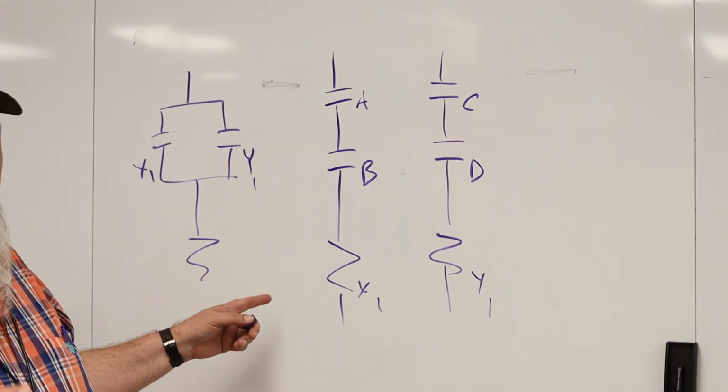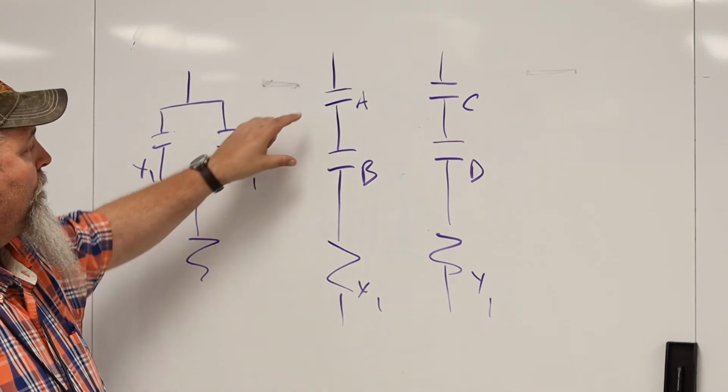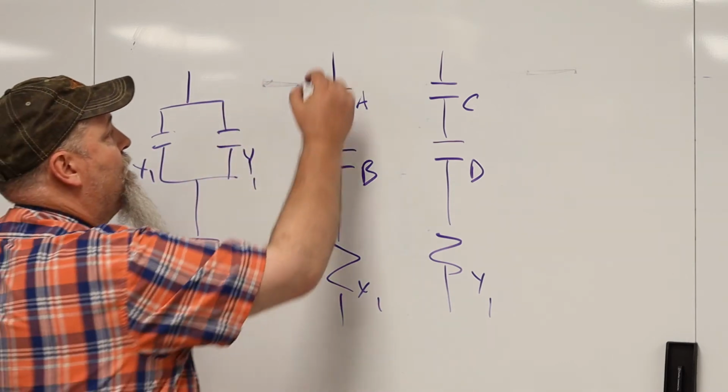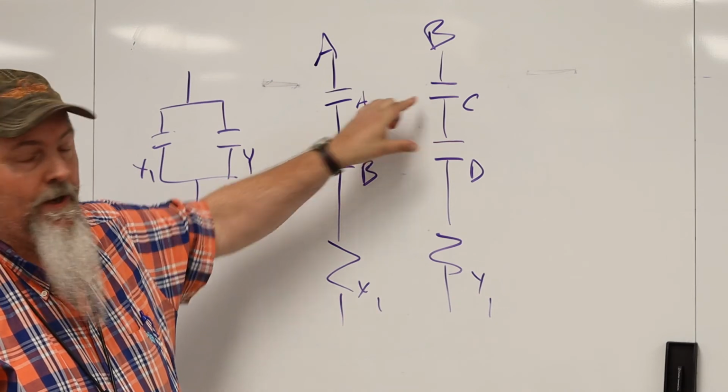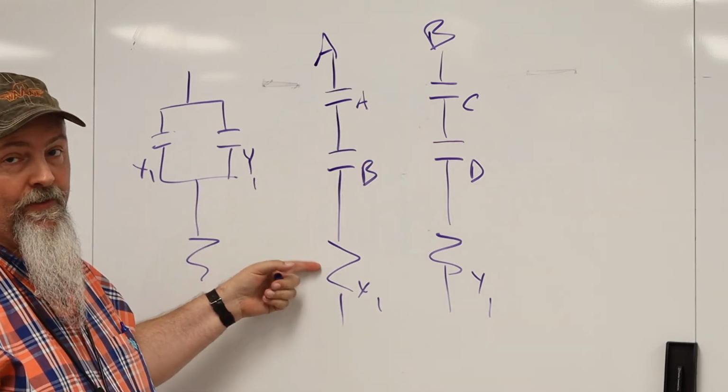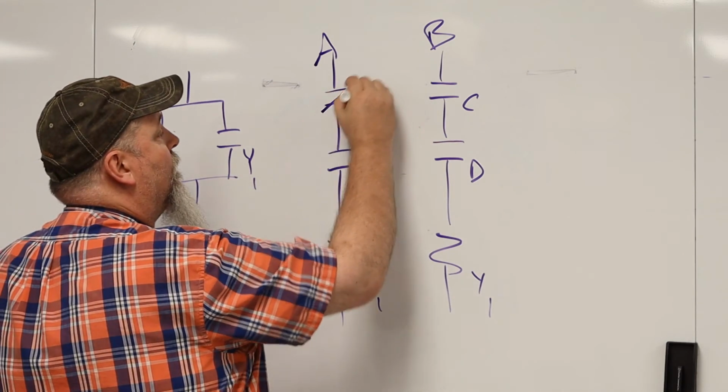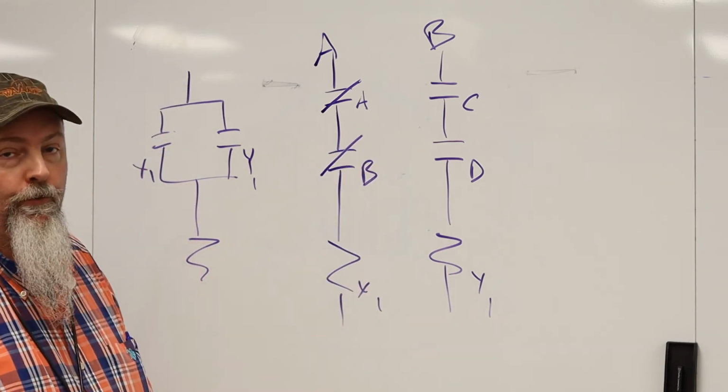So a 2 of 2 once. There's 2 in this logic channel and 2 in this logic channel. In order to energize this relay, I need both of those closed.